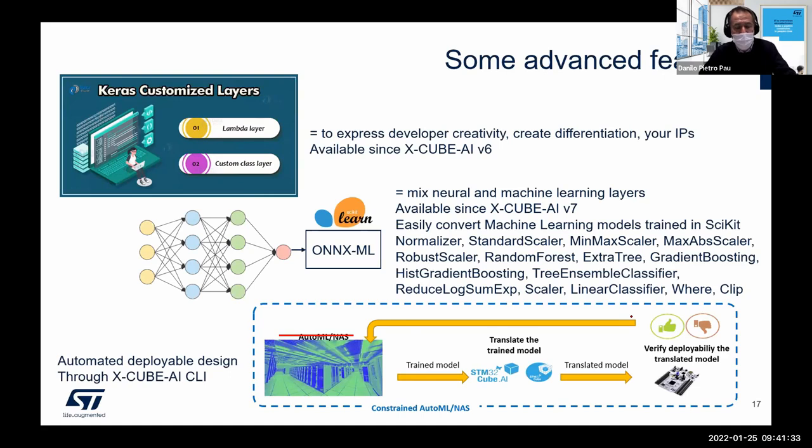And then measure the properties: occupation in RAM, occupation in flash, execution time. These set constraints, and if a tool that does neural architecture search considers them, it can converge more quickly because it is optimized, knows what the costs of the different solutions it is developing are, and so concentrates not only on accuracy, but also on deployability.